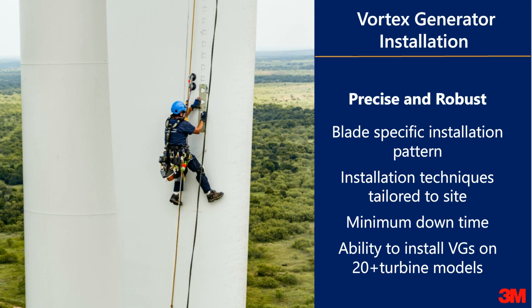So as Santosh says, we do a SMARTviz on each turbine model to ensure that we have the optimal placement of those VGs. Currently, we have the ability to install VGs on 20-plus turbine models. And for each of those turbine models, we have a blade-specific installation pattern that we use. And our technicians are trained with the help of our internal trainers, SmartBlade, and 3M to ensure that they are trained up on each blade-specific installation pattern.